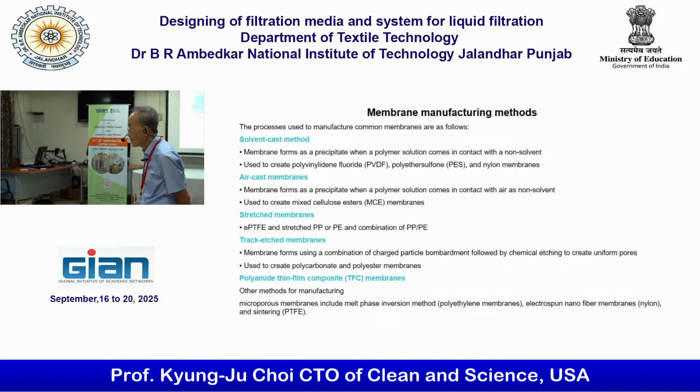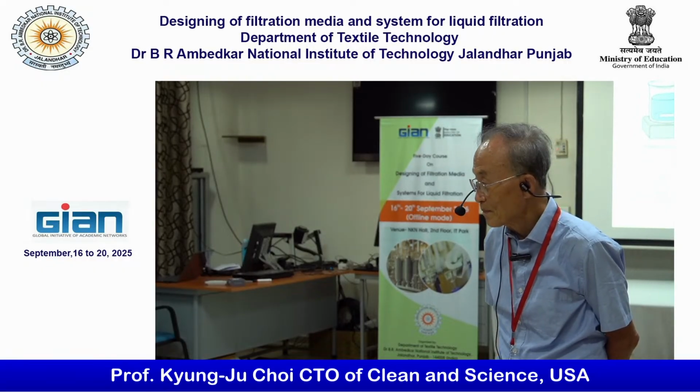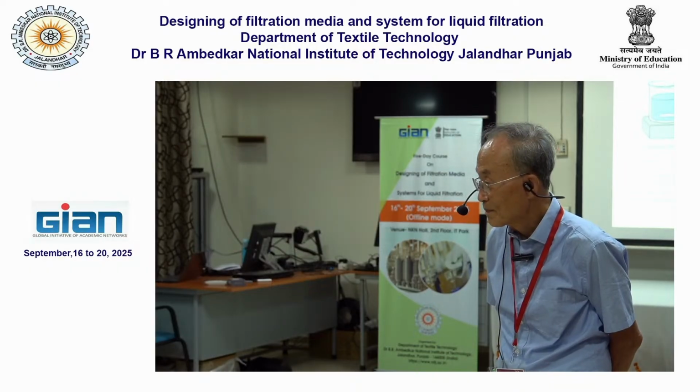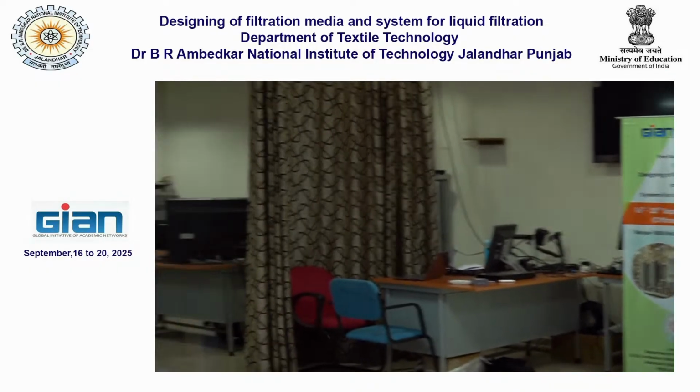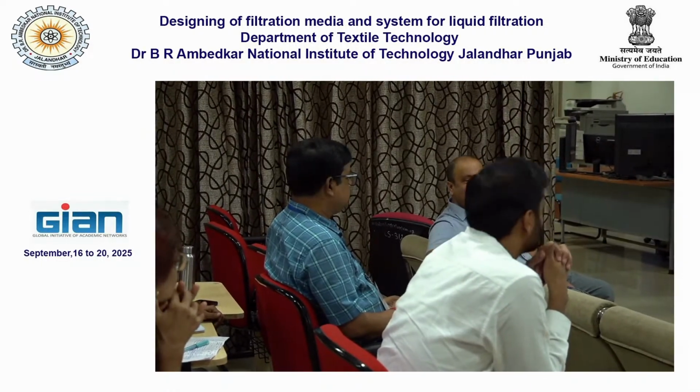Osmosis is different. Normally osmosis is without the application of pressure. It depends on the concentration. One will flow from one side to the other side. Whenever you apply pressure on the higher concentration side, obviously it will work in the opposite manner. That is why reverse osmosis came into the picture. Nowadays people are also going for forward osmosis. You deliberately increase the solute concentration on one side, so that the water can move from the pollutant side to the clean side.